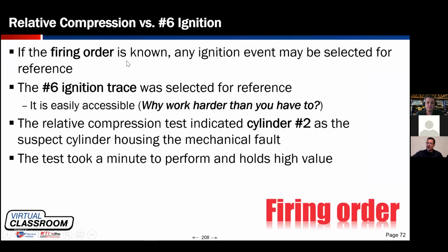So I know the firing order, and we have an ignition sync. We can easily determine that cylinder number 2 does not make the starter work as hard as the other 5 cylinders. So we're going to pursue a problem with cylinder number 2.